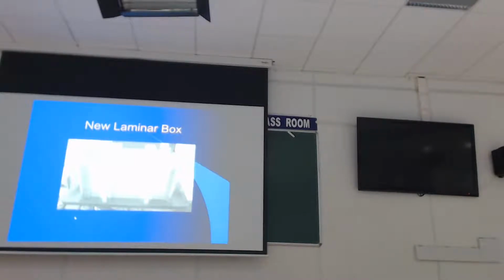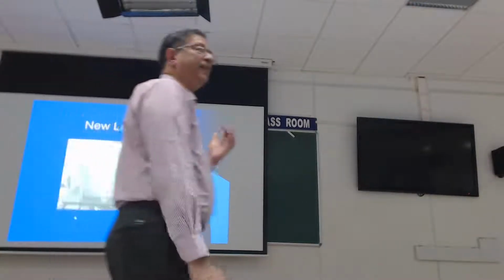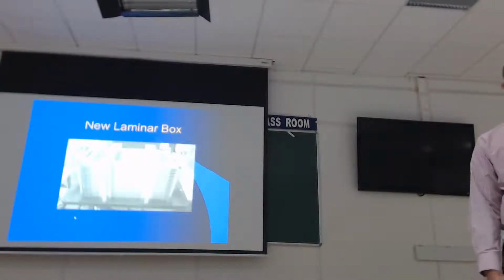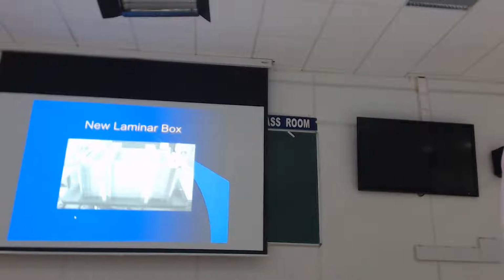There are some safety end stops on the right. Just about here you can see them. If the box goes too much, it will stop it from coming off the centrifuge. Of course, you don't want the box to disintegrate and fall everywhere on the centrifuge. That would be disastrous, so we have these end stops as a safety feature. But again, this is something you want to think about, even if you're thinking of doing 1G shaking table tests. Boundaries are very important.